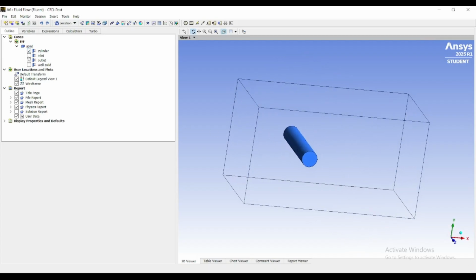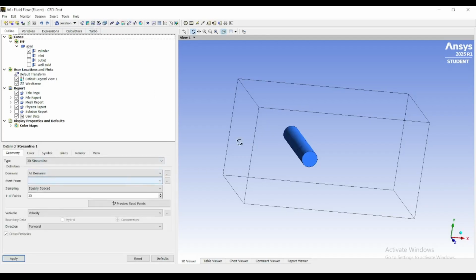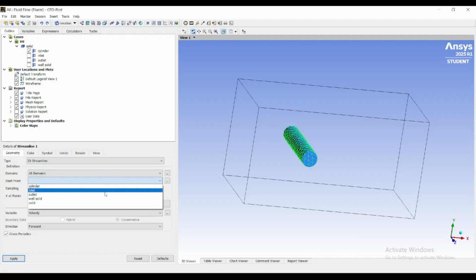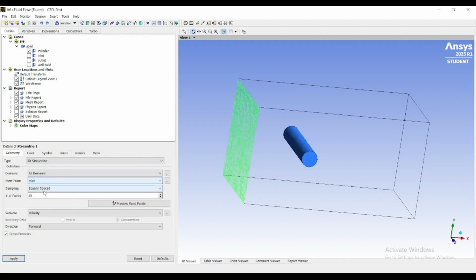In laminar flow, separation occurs early, leading to a larger wake and higher drag. In contrast, in turbulent flow, the boundary layer stays attached longer before separating, resulting in a narrower wake and reduced drag. This concept, called drag crisis, plays a critical role in aerodynamic design. For example, the dimples on a golf ball help maintain a turbulent boundary layer, delaying separation and thus reducing drag. A principle you can observe in your Fluent results when comparing different flow regimes.